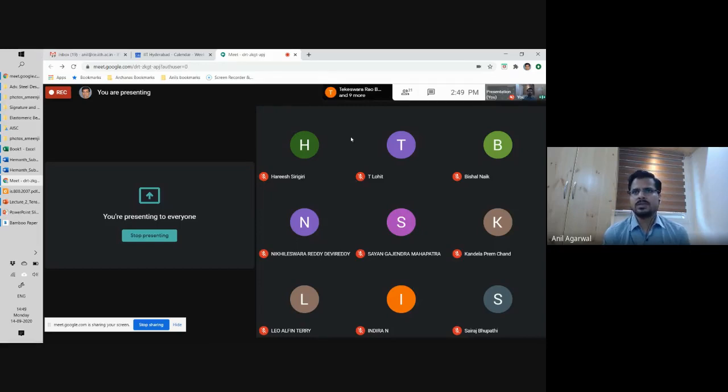So if, for example, the strength limit state is exceeded, so I design a structure and I apply the loads, and somehow I made a mistake in designing or whatever, or loads exceeded, whatever. And the strength limit state exceeded and the structure failed the strength limit criteria. Okay. And when it fails, it will have some kind of a damage. And as a result, the structure will not be usable. Okay. It will not go back to its original state.